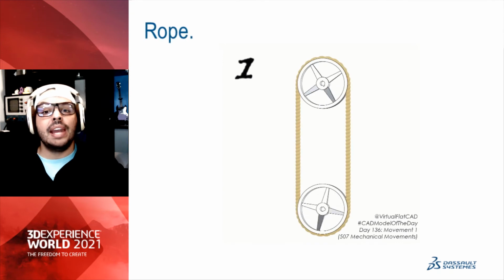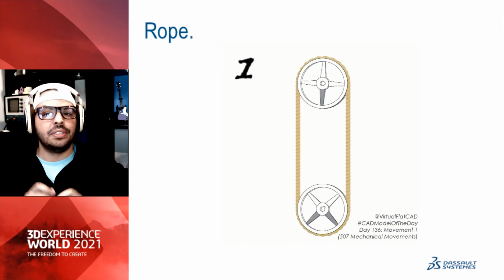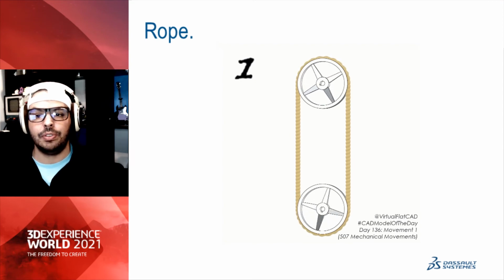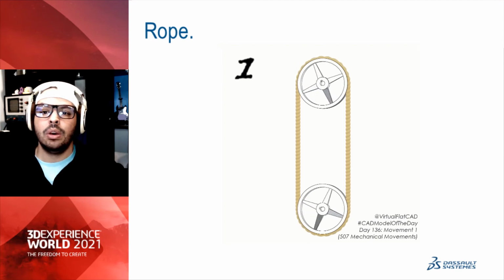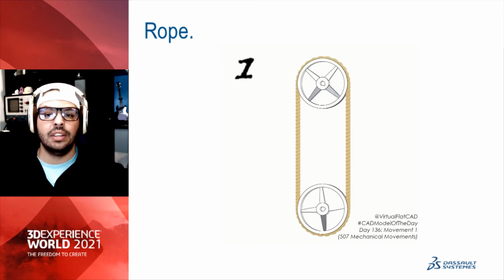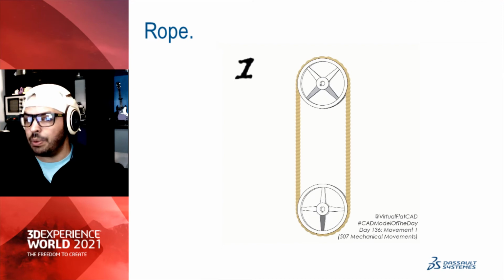We are going to animate rope in SOLIDWORKS. Now, before you go to the comment box, yes, I do know about the belt and chain feature for assemblies. This is not that. Belt and chain is designed to work with a constant cross-section belt or the discrete linkages of a chain. We need a strand of rope of constantly changing cross-section to move along a path. Are you ready?